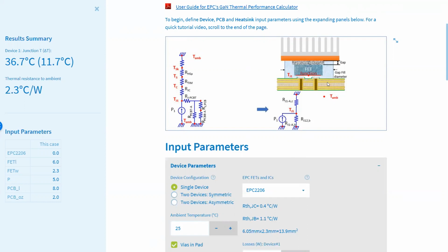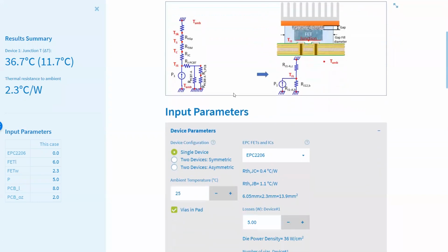The different parameters of the cooling solution can be modified later, and the schematic will update accordingly. Also, the thermal resistances of different structures through which the heat will be conducting from the junction to ambient are also represented in a circuit diagram. And this is what is later solved for the overall temperature rise in the active devices.